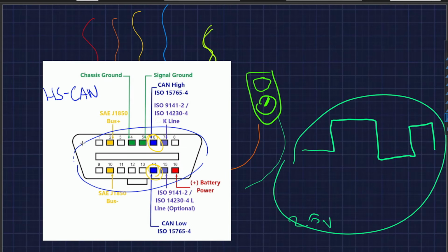So, gateway ECUs often isolate them intentionally, right? This is where wiring diagrams of your car become essential, and factory service manuals are gold. Without them, you are just guessing. I have spent hours tracing internal controller area network lines behind dashboards because the bus I needed was never exposed externally. Now, this is normal work in real vehicle research, but it's not that hard, right?